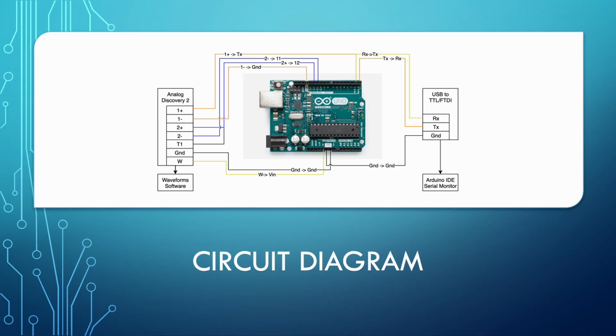The oscilloscope 1 channel monitors the serial connection so we can detect when the user inputs their password. Channel 2 monitors pin 12, and the reason is sort of a contrived way of finding when to trigger the glitch. In the code, we set pin 12 high right before the if statement where we check the password, and that helps us tune the glitch timing. Once the user enters their password, we need to skip the comparison instruction to enter the authenticated code section.